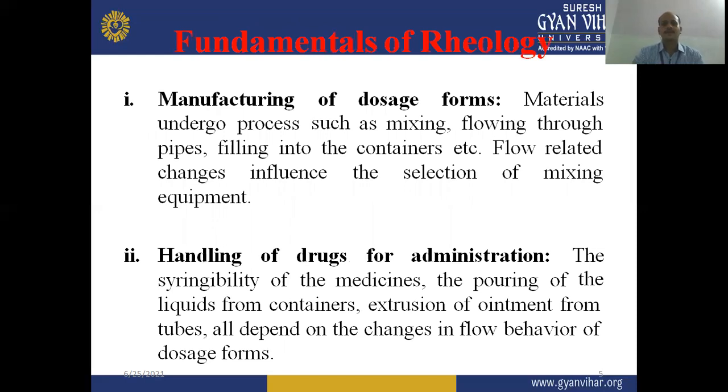Then when we discuss the fundamentals of rheology, as we discussed, rheology is the branch of science which is related to liquid flow or deformation of solids. Some fundamental aspects of rheology are given here. In manufacturing of dosage forms, materials undergo processes such as mixing, flowing through pipes, filling into containers, etc. Flow-related changes influence the selection of mixing equipment.